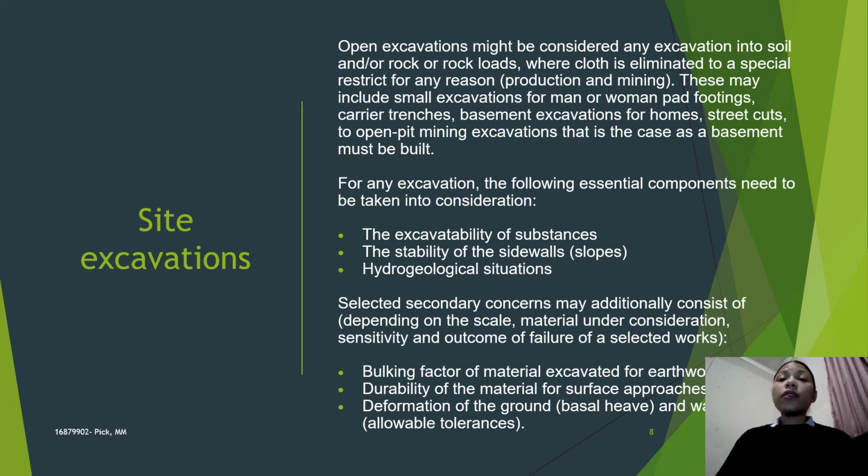So the following essential components need to be taken into consideration: the excavatability of substances and the hydrological solutions, as well as the stability of the sidewalls and slopes, as I've just mentioned. And then selected secondary concerns additionally consist of the following: bulking factor of material excavated for earthworks, the durability of the material, as well as the deformation of the ground.